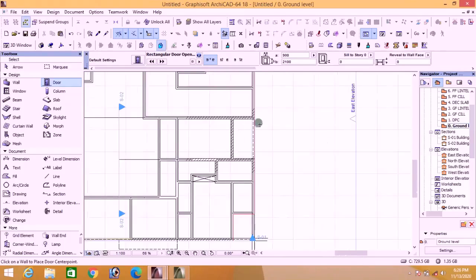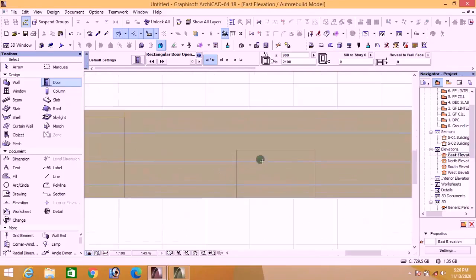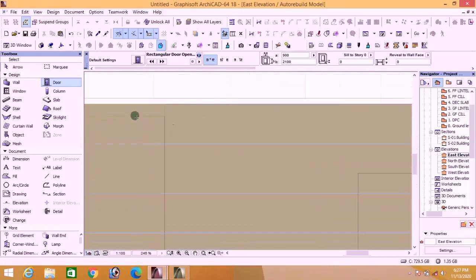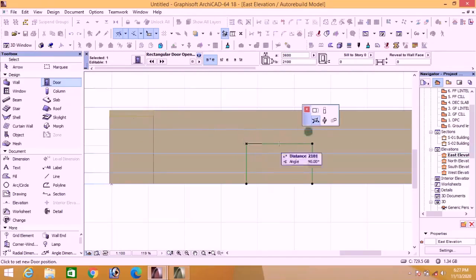Then to see this beam and set it, finally go to east elevation. Can you see where it stopped? Now we want it to stop at this level, at the level of this beam here. Can you see this beam here? So right click on it and click at this spot, change it to stretch vertically. We are stretching it up, stop at this level.